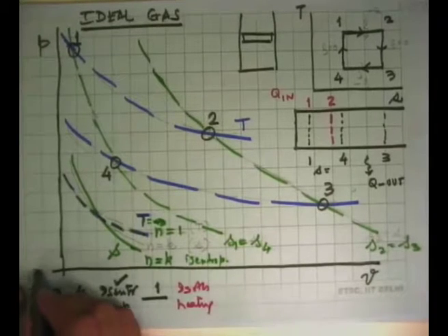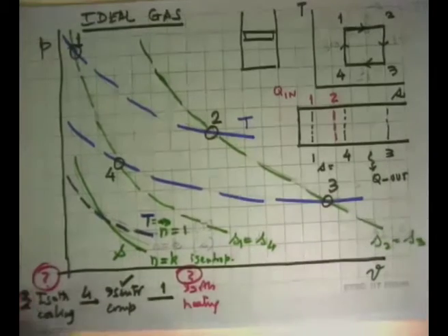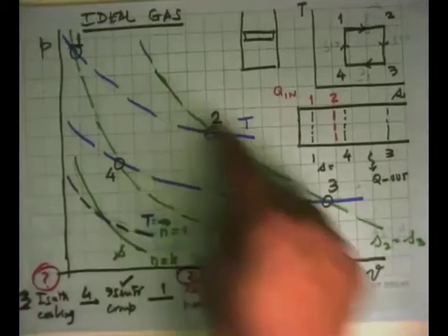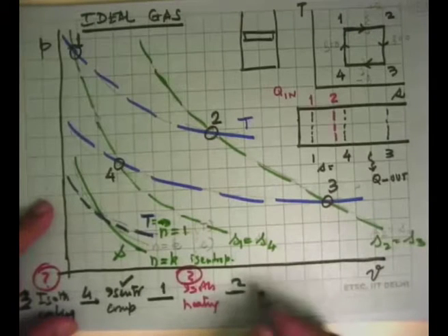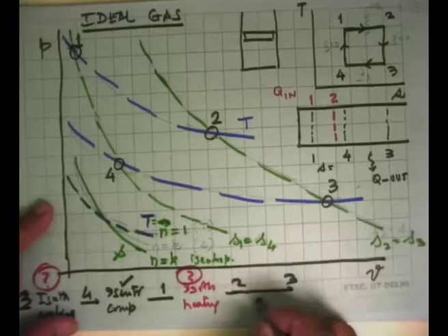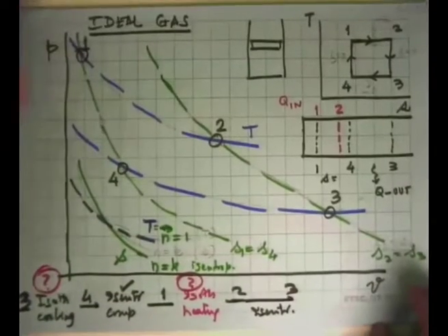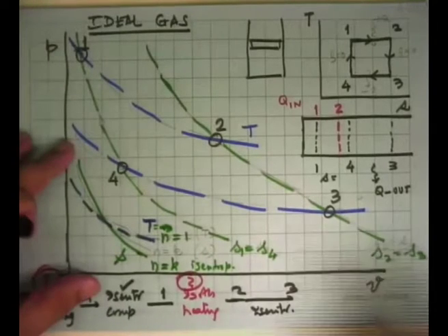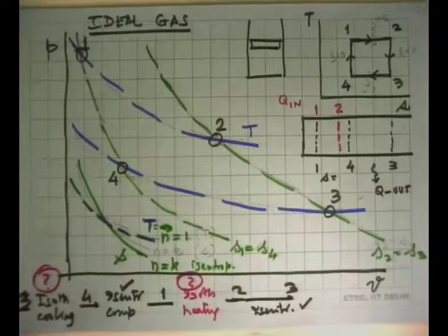So this is a big question mark, cannot do. Isothermal heating is the next big question mark, we cannot do it. And then 2 to 3, this is isentropic expansion, and we can say, well, not isentropic, but I won't take out heat from it, I won't cool it, but yes, I can get very close to it, not n equal to k, but slightly less than k.